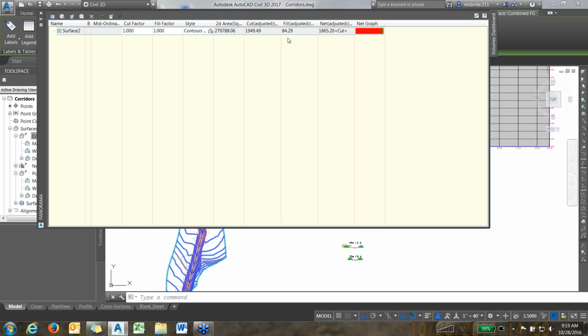And as far as are they correct values, typically on a grass waterway, can be anywhere from like 1.2 to 1.4, 1.5 cubic yards per foot. So if you do some backwards calculation, I think this is in cubic feet. Nope, it's in cubic yards.